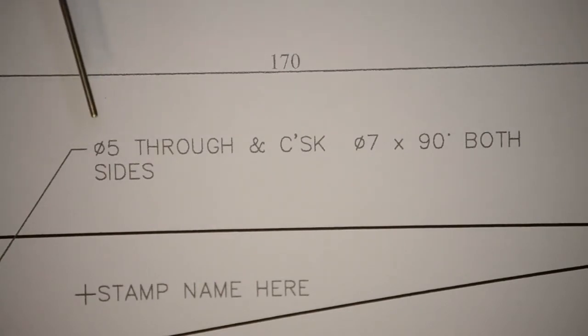You can kind of imagine, I suppose, if you need something to jog your memory, that it's a hole that somebody's laid a rule across to measure it. So that symbol there is known internationally as meaning diameter. It's one of the key British standard, ISO, ANSI, you name it, symbols that tell everybody who's working on any kind of engineering drawing that we are talking about a hole with a diameter of, in this instance, 5mm.